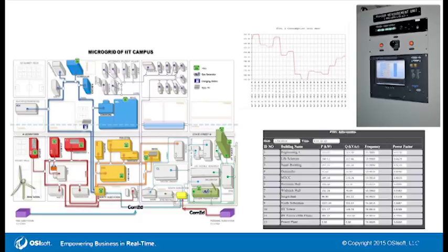So what their microgrid controller does is it runs on 3 levels, right? You have the second-to-second, sub-second control of level 1. You have 4-second control that's responding to how the state is operating at that point, and then economic control at the minute level for the paybacks, right? And as you work your way further up in time scale, the signals can travel longer distances to more participants in the conversation.